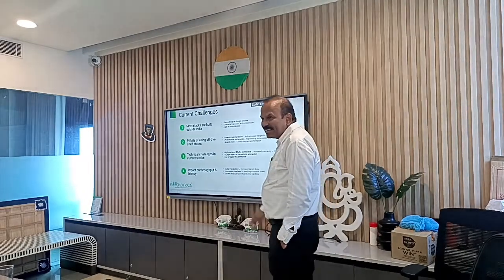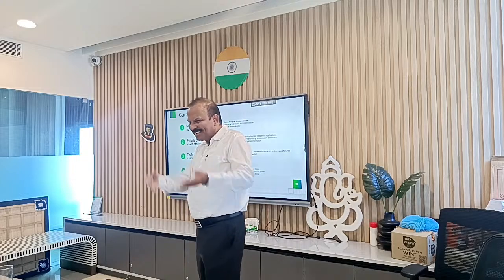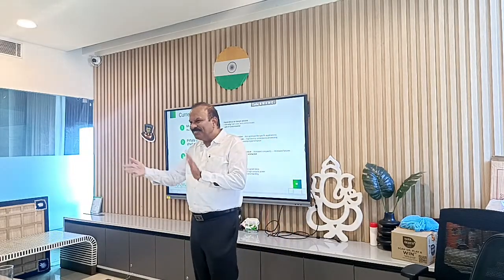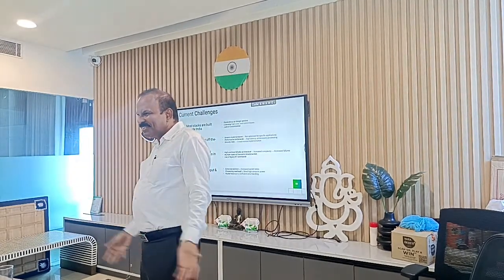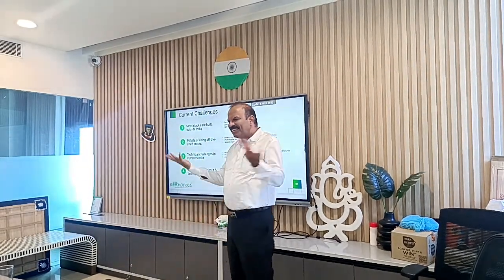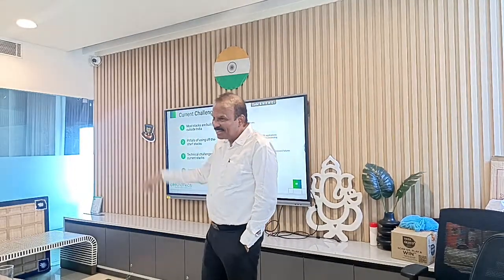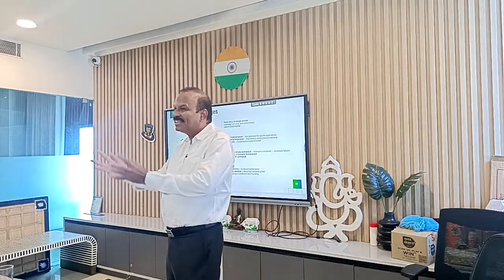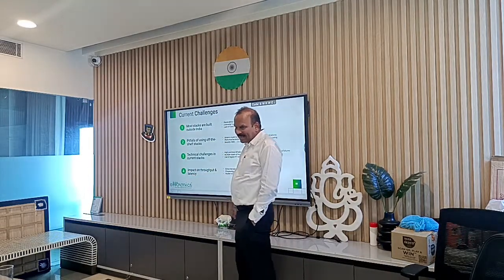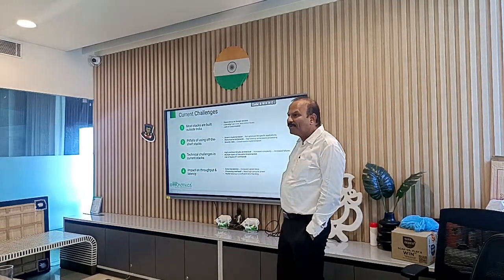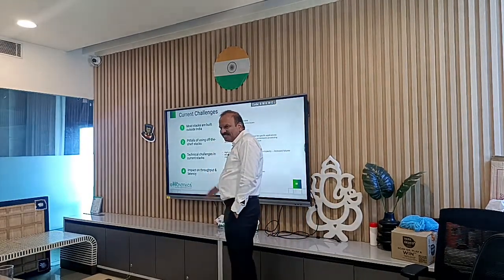Impact on throughput and latency. At the end of the day, that is more important. When you want to communicate, latency is more important. The moment I want to take action, the others should respond. If it is taking more time to translate and send that information, naturally you can't control it, because the cycle time of the control is going to be high. If cycle time is high, you have a lot of other challenges. So throughput and latency are critical aspects which we observe in most of the systems we build. That's the extra translations we are discussing.